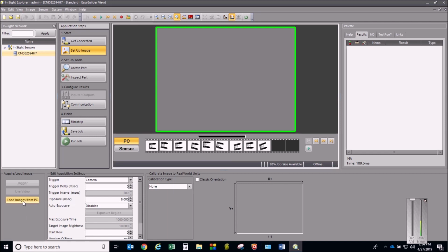And as a reminder, if you are working with an actual camera, the most important thing when working with machine vision is lighting. So the ambient light is what you want to try to either eliminate or completely control. We can eliminate ambient light by putting our vision system inside of, let's say, a smoked windows plexiglass enclosure, and having LED lighting from inside.